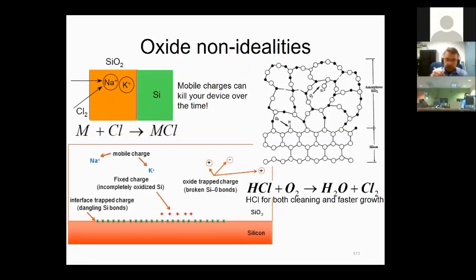Okay, one thing before we do the MATLAB, we also flow in the HCl, if you remember. People were really worried that their transistors were not functioning properly in the old days, like in the 1960s, 70s even. They weren't sure what the cause was. The cause was these kinds of mobile ions that can be introduced from anywhere. Like if you work with a beaker in your lab, you can't avoid these mobile charges. Once they enter your oxide, like sodium, potassium, they will be under the influence of the electric field. They'll just propagate.